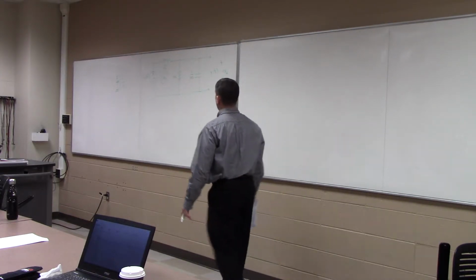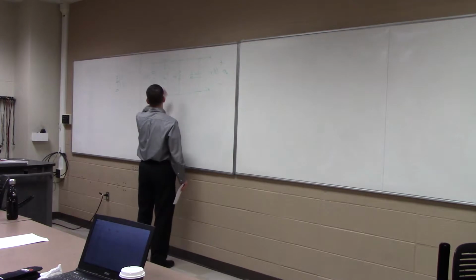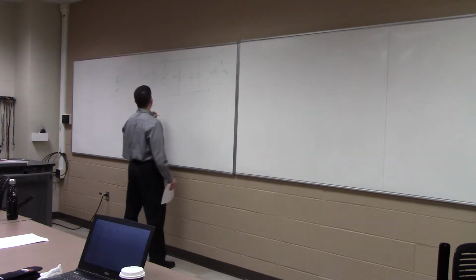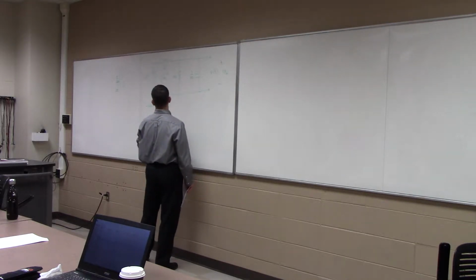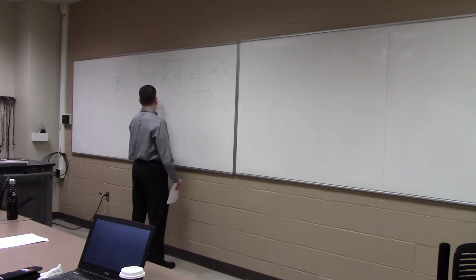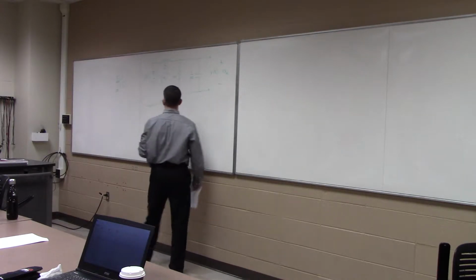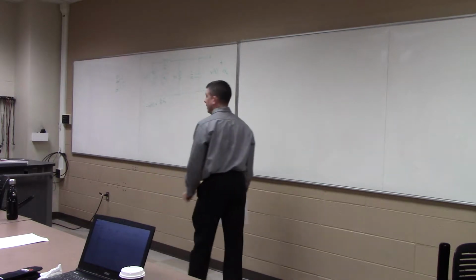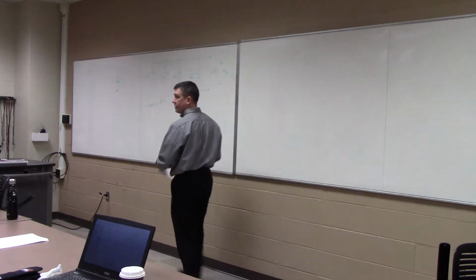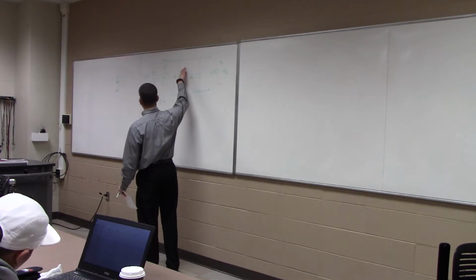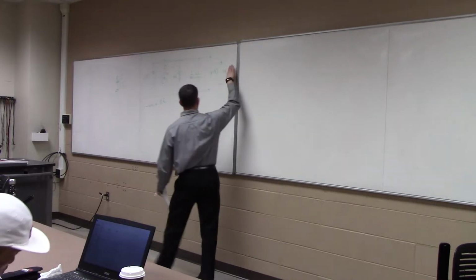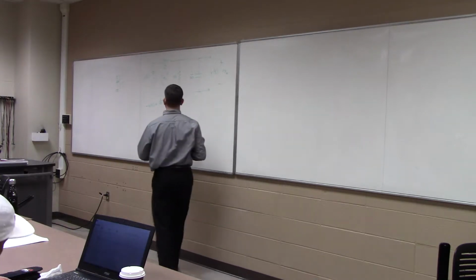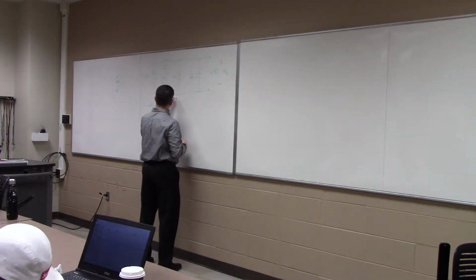So, Kirchhoff's voltage law going around this mesh, it's negative u of t plus L di/dt, so that's going to be 1/10 x1 dot. And then I have to do the voltage drop across this capacitor. That voltage drop is going to be x2, right? x2 is the same voltage drop across that resistor. So plus x2 is equal to 0.